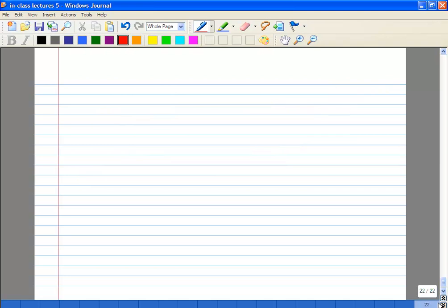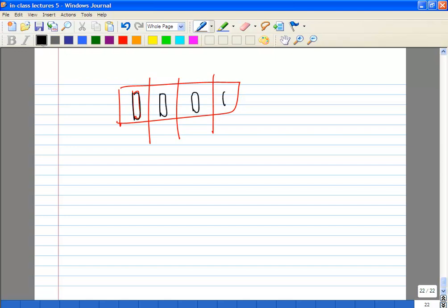What else? You can fill. Obviously, we looked at filling on the bias circuits. The other thing to know for transistors, don't stack up too many metal lines on the drain source, okay, because you'll have extra capacitance to the gates. Fill up just enough so that you meet current density requirements.